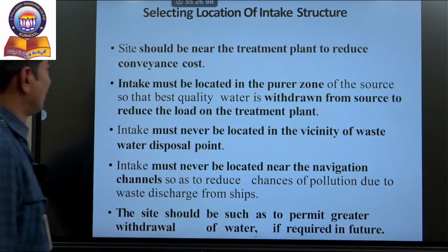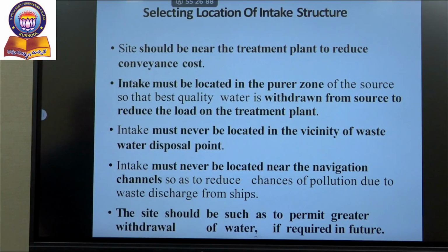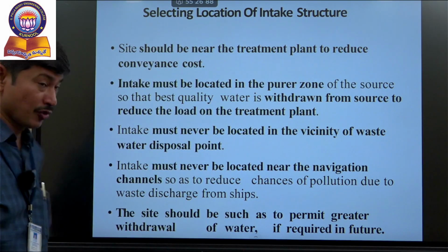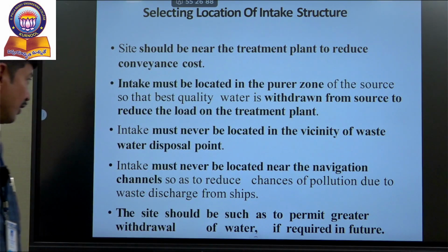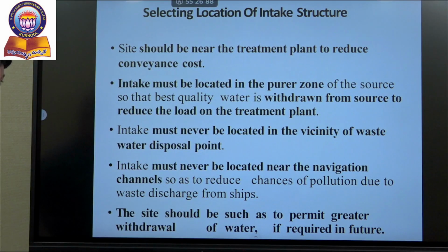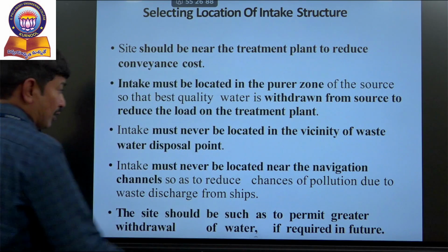Selection of site for the intake well. The site should be near the treatment plant to reduce the conveying cost. The intake must be located in the purer zone. It should never be located in the vicinity of wastewater disposal, nor near navigation channels or at curves. The site should permit greater withdrawal of water even in the summer season.